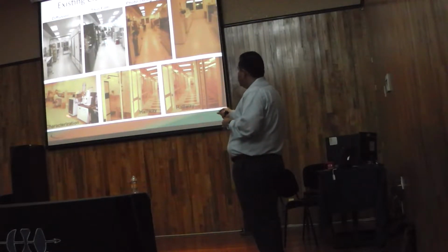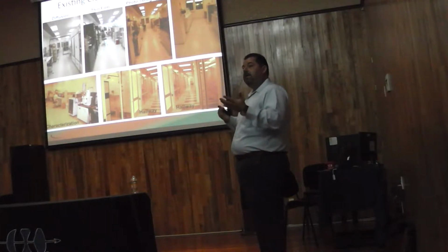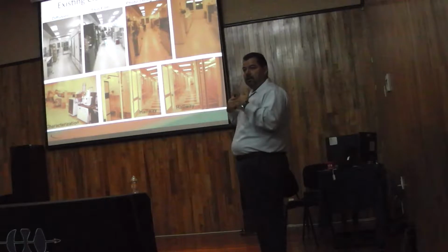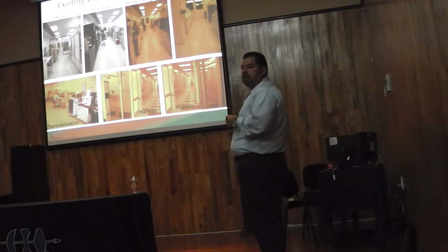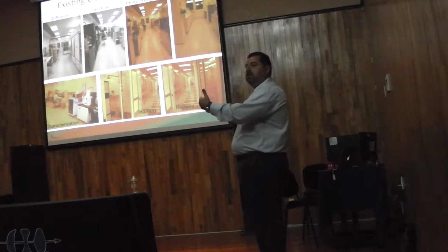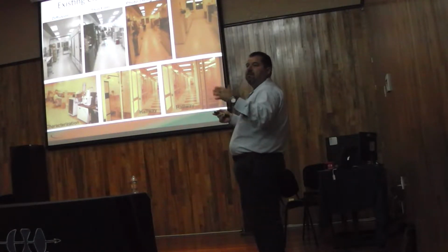Inside the clean room we also have a characterization bay. So if for some reason I deposit the film, and I suspect that the film may be thicker than the thickness that I was trying to deposit, I simply go without leaving the clean room. So these are the bays that I'm showing there. The door there is the access to the characterization bay. So I can take the film to the SEM to look at the thickness or to look at the roughness.